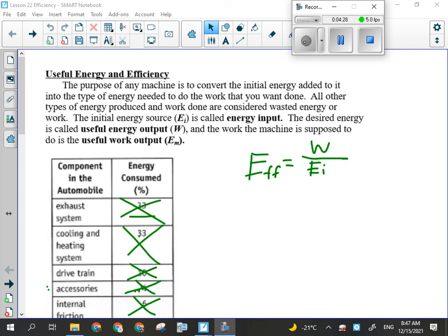And when there's a lot more heat, the metal expands and makes that pressure even greater, more and more friction, until parts of your engine just destroy themselves, okay, and try to exit the motor, right, making big holes in it through which oil and other important fluids will leave, okay, and that'll be the end of it. If your motor seizes, that's what happens if it doesn't have oil in it, okay, you can't fix that, it's done. So we need to have ways to reduce forces that cause us to lose efficiency.